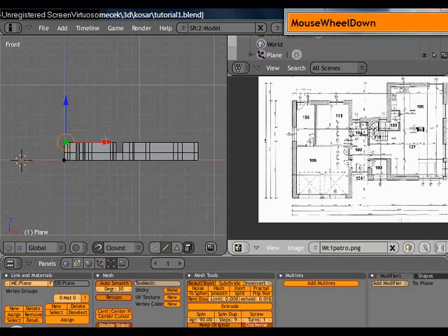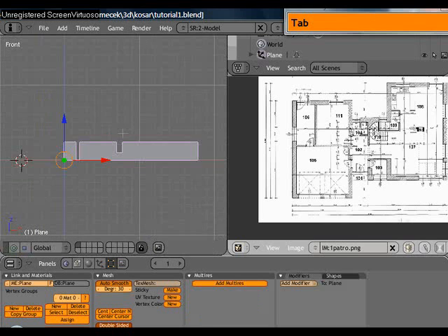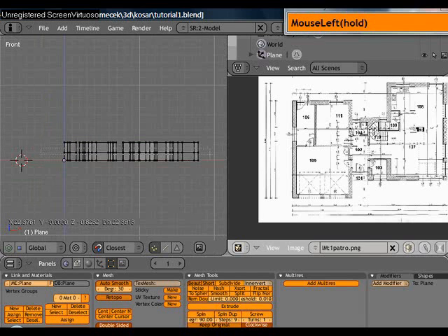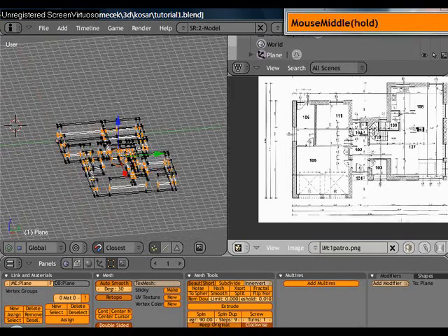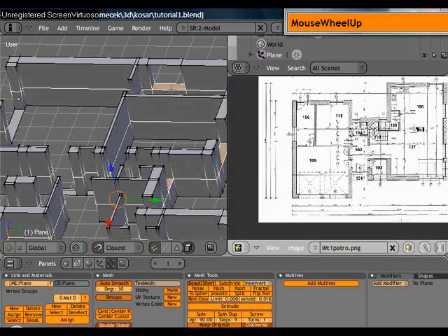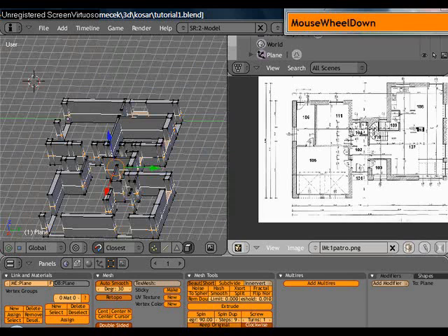If I tab to, I'll go to wireframe mode, and I will go to select vertices. I will select this part of the house where I have those faces over here, and I will duplicate them and move them up, so I'll copy them on this top part.